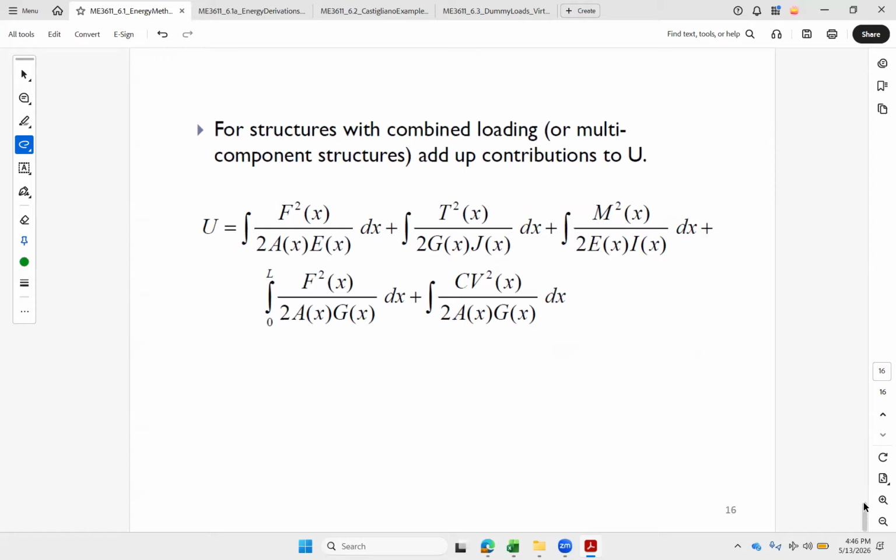Very often in a beam, we're going to have some shear force creating a moment. We might have both of those. So everything could just be linear addition, linear superposition of those. So any combination of loads, we just add them up for a given.